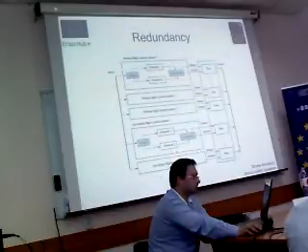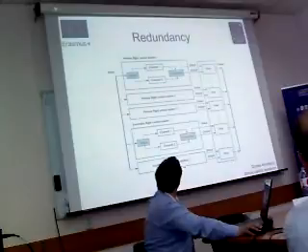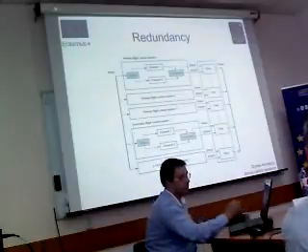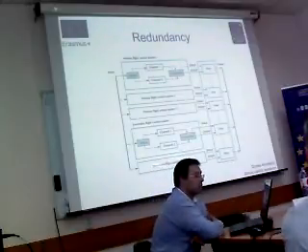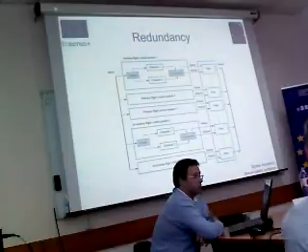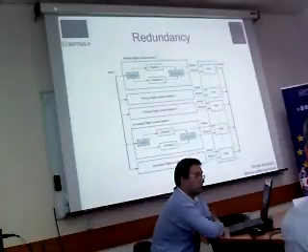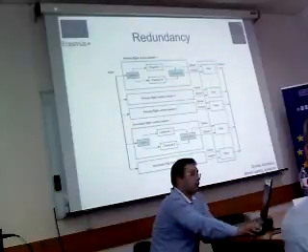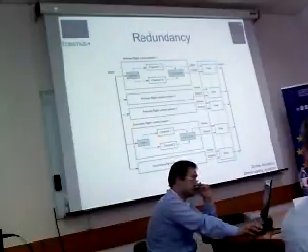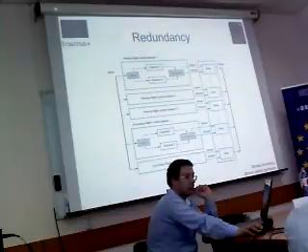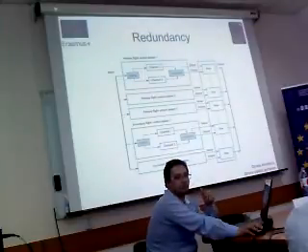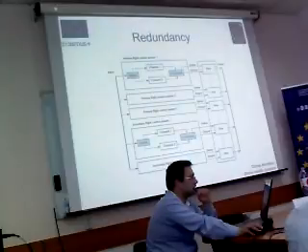So as an example, in the case of this Airbus aircraft, besides the three main flight control systems, two backup systems are available to help isolate the faulty one. Inside each, there are two channels which run software written by a different team or run on a processor different to the one in the other channel, and which are supplied by two different suppliers. So this solution helps to reduce systematic errors, when all would fail altogether because of a common malfunction.